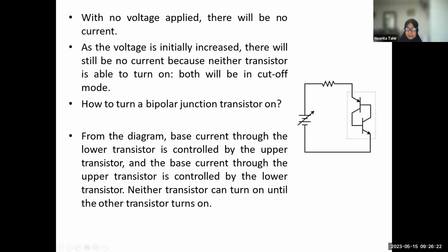So what happened? Once one transistor breaks down and begins to conduct, it will allow the base current through the other transistor that will further cause it to turn on in a normal fashion, as a normal transistor, which then allows the base current through the first transistor. So at the end, both transistors will be saturated, which keeps each other on instead of off.